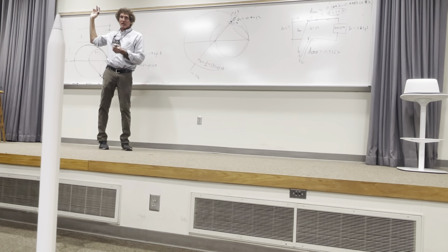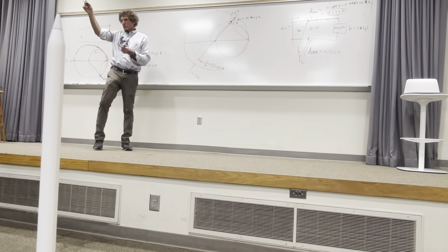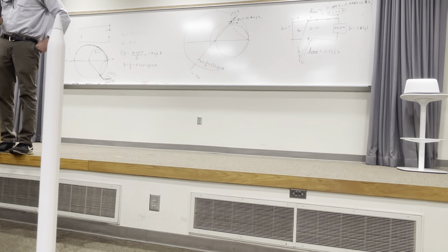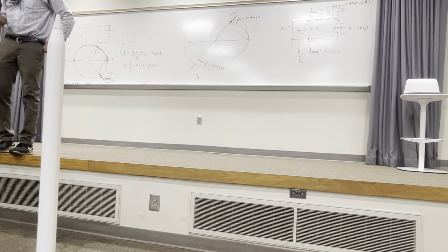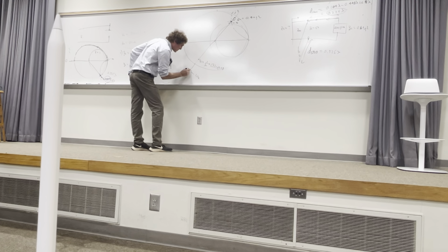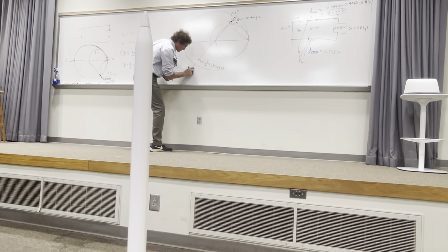That's high. What did you get? Remember, it's wavelengths toward generator. 436? Yeah. 435, something about that? We'll go about 0.435 lambda. Let me make that a little larger. And that's wavelengths toward generator.